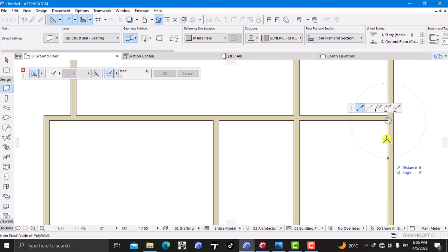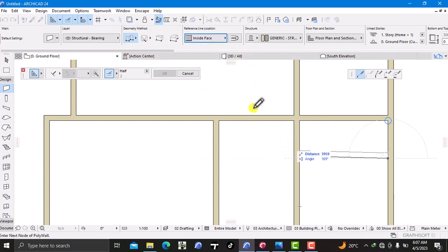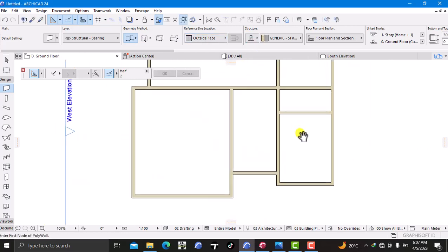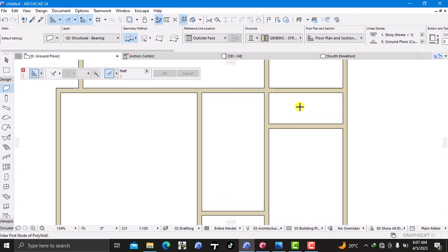Change the face, work with the outside face instead. So I'm going to have something like that. Yeah, so that I have my corridor over here, and then I need to do another typical one over here. A distance of from this edge, a distance of 1200, 1200, enter.